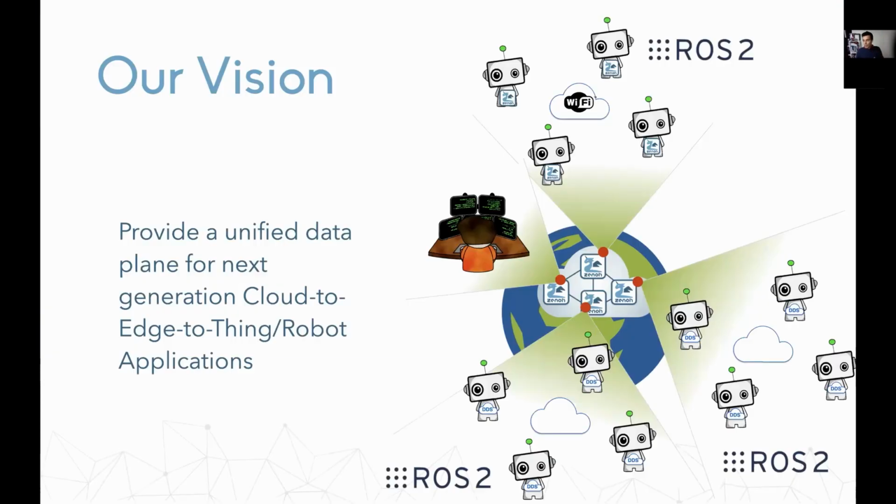Okay. So if we put all of this together, essentially, you see that now, thanks to the nature of Zenoh, you can use Zenoh in combination with ROS to avoid all the challenges on Wi-Fi. You can use the Zenoh plugin for DDS, as DDS is the default transport for ROS, to bridge your robots or your ROS-based autonomous vehicle, whatever it is, essentially very efficiently through the internet.